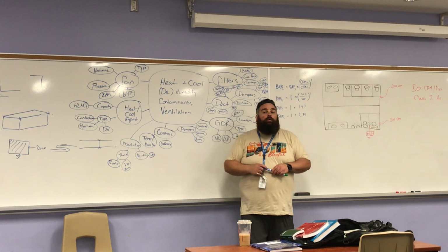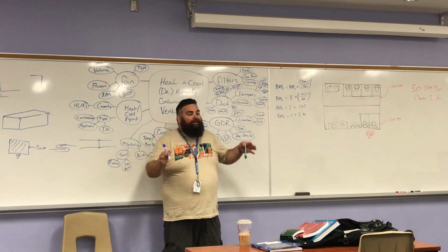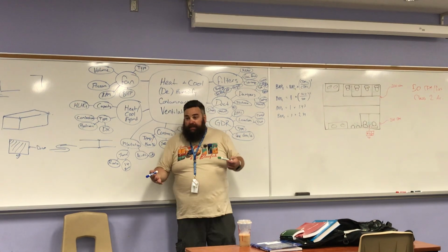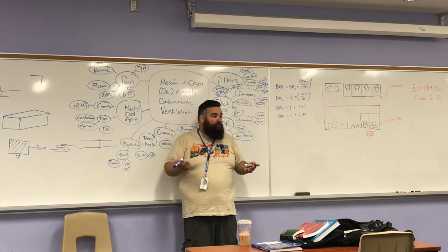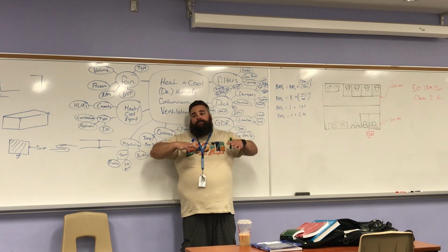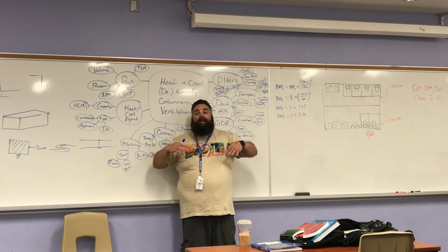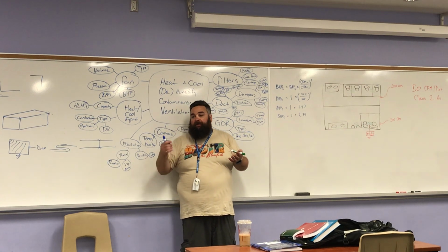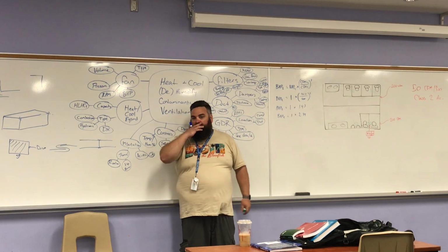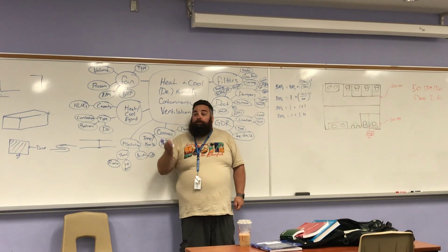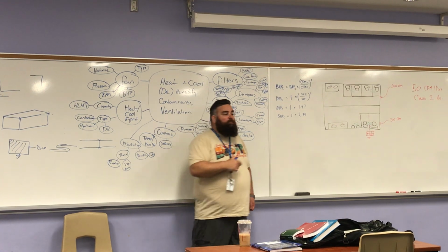Okay? We need somebody who can cut a hole in the roof and then restore that membrane so it's watertight. Now, roofing comes in many different shapes. You have built-up roofing, where you'll have your insulation, a membrane, and then tar and gravel over top of it. You might have an EPDM type of roof membrane, like that white membrane that gets laid down on the roof. So you need somebody who can put that penetration in and seal it up, okay? So there's a cost there.